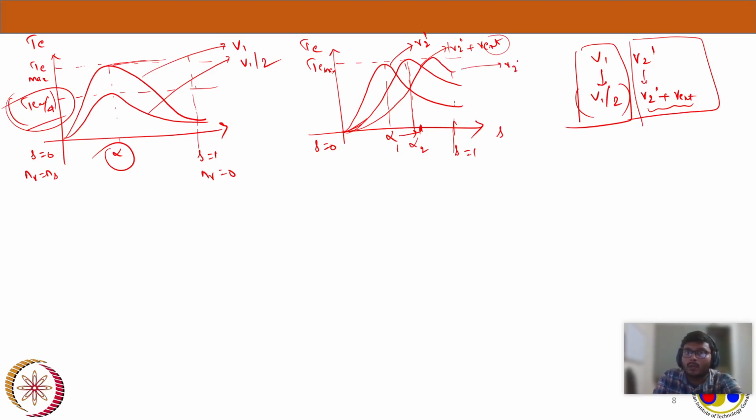This is for R2 dash plus 2 times R external. Let's say I have increased this two times. Now if you see one interesting thing we observed even in the last week, as you increase the external resistance in the rotor, your starting torque is getting improved. You can also see that from the curve here.